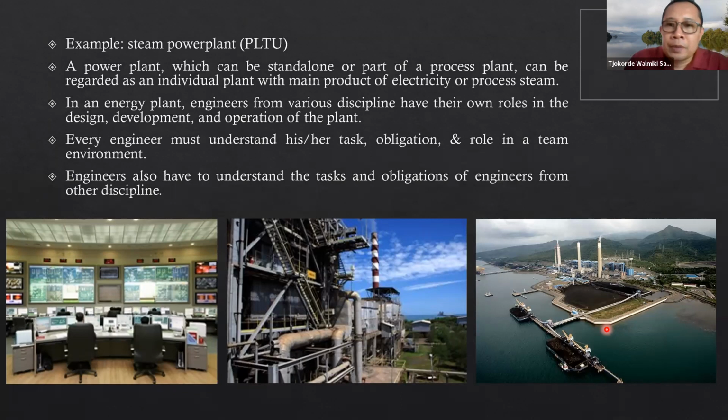So do not do what one of my rancangan pabrik advisees did several years ago, where they designed coal storage in the form of aluminum tanks. And I said, okay, question number one is why tank? Question number two, why aluminum? The tank itself is not reasonable to be used with coal, and aluminum is way more expensive than stainless steel. I'm not sure where these guys get their idea that it's good to store coal inside an aluminum tank. That just doesn't make any sense.